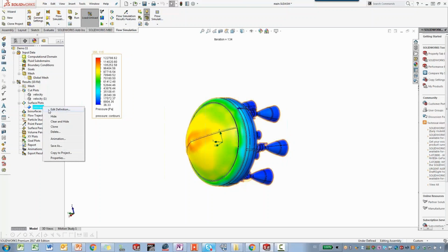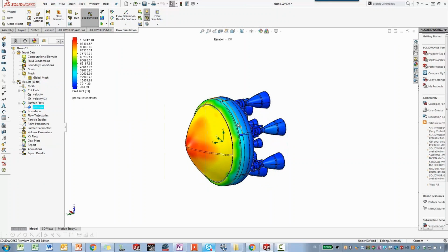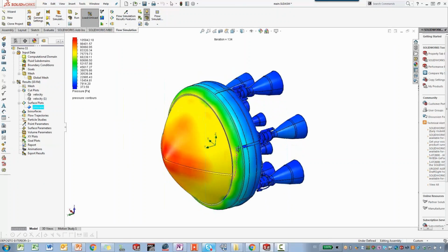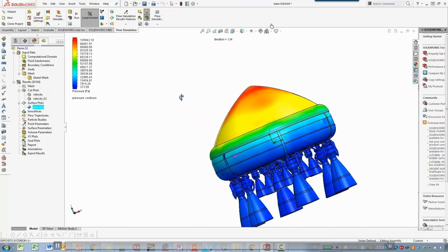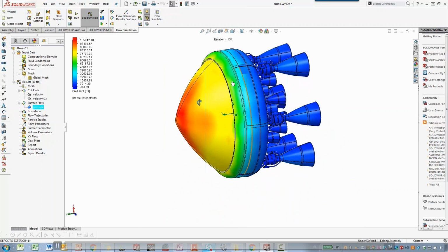Which is good actually. We can take these results. This is another benefit of using SolidWorks Flow Simulation, to take the resulting pressure directly into SolidWorks static analysis, which will use SolidWorks Simulation. Perfect. And another type of result actually is to probe. So for example, if I'm interested in a certain area, I can probe and have only the pressure on this certain area.